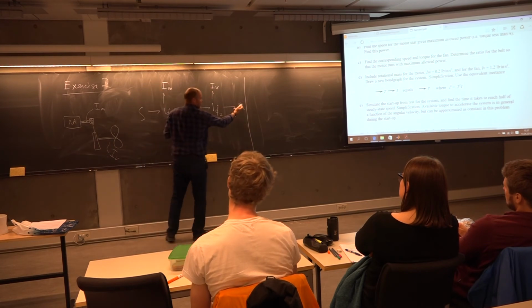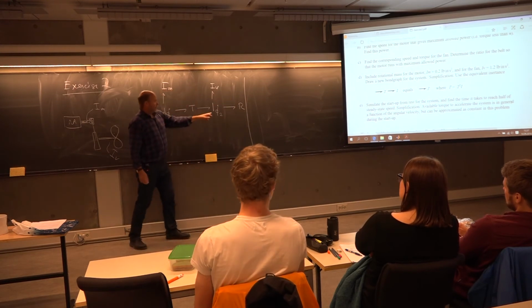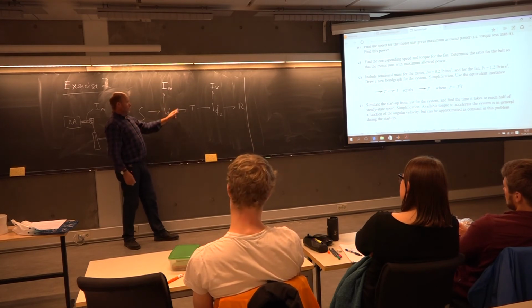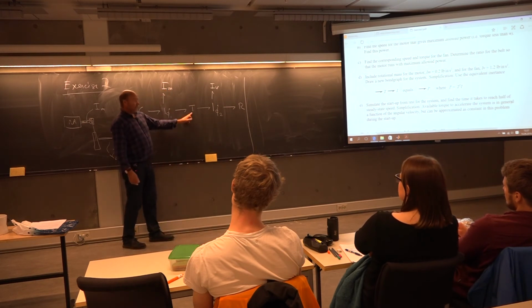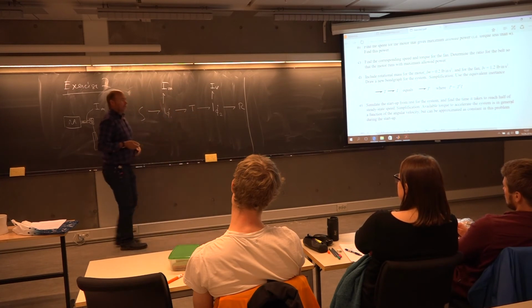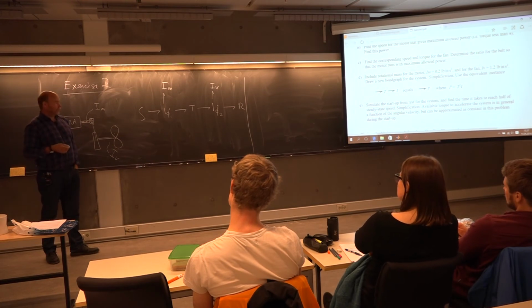For the resistance, we have one equation, a coupling between effort and flow. For the one junctions, you get one algebraic equation. You sum all the efforts around the one junctions to get 0. For the transformer, you will have two equations. So all in all, a whole bunch of algebraic equations. That will be one way to solve the problem.